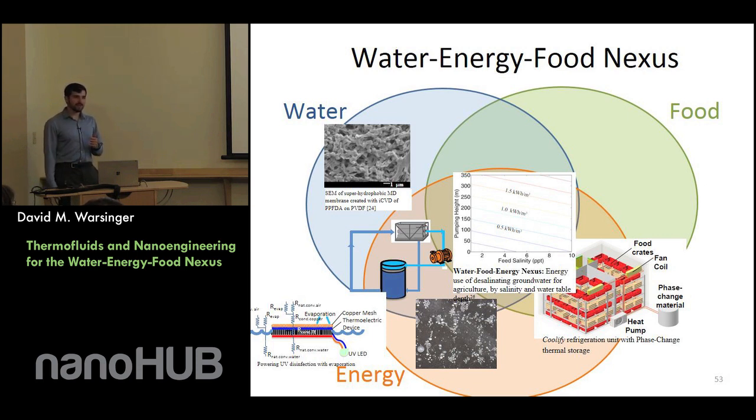One of the problems I've been hitting my head against a wall with for a very long time is how can we use the evaporation of the surface itself to power disinfection, so we can have a kind of silver bullet type device that can disinfect anywhere. The thermoelectrics were unsuccessful because the second law efficiency at low delta T's becomes zero. We recently did a Stirling engine cycle, and essentially to make that really work, we had to start adding warm water or near boiling water, and we can get very good ratios. Like it could disinfect with 1/8 the energy it would take to just boil the water. But we're still not there yet on disinfection, but it's an active area of interest.